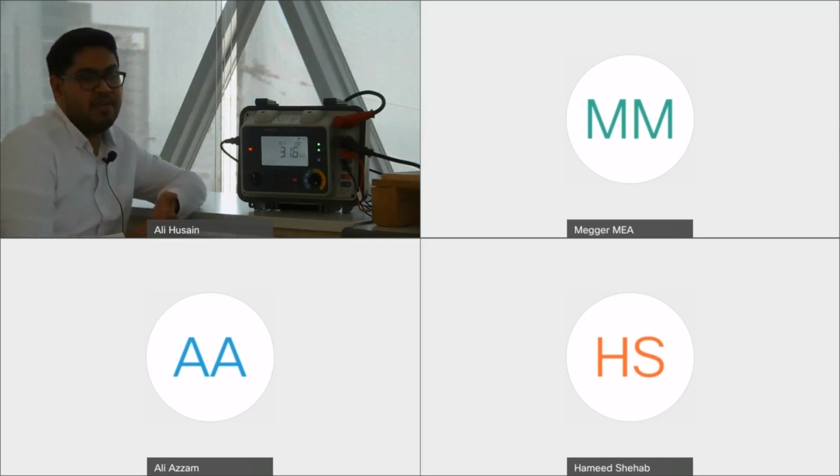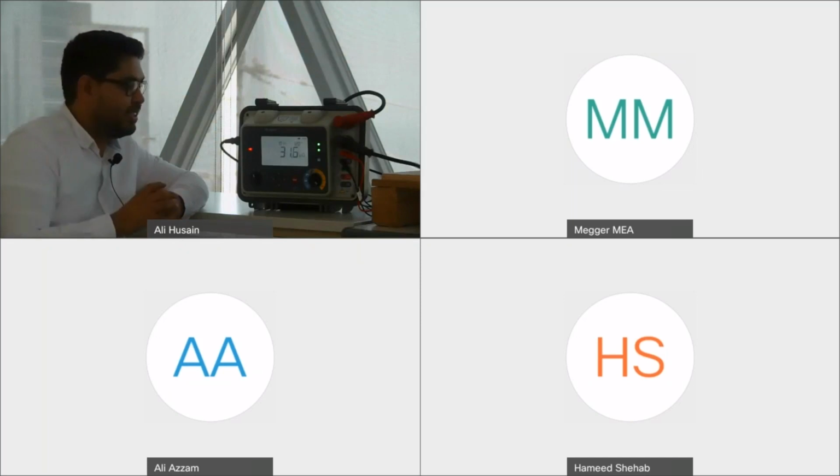This is very important when you are working in an energized substation, since in this case, any induction or any capacitive coupling currents flowing from adjacent live parts will not affect your results and measurement, and also will not create a hazard area for you. So it is always recommended to do these tests in dual ground conditions.